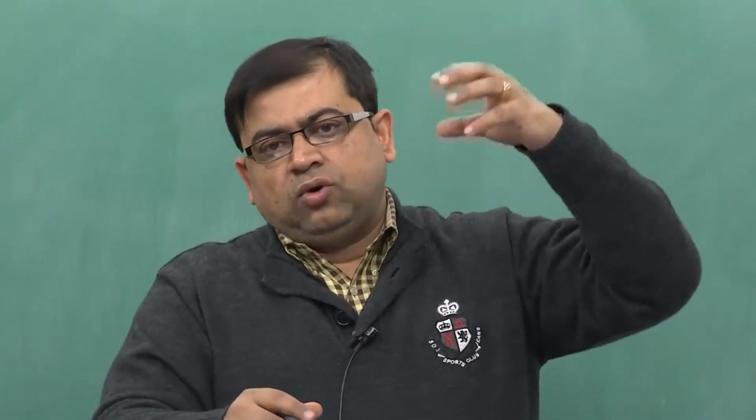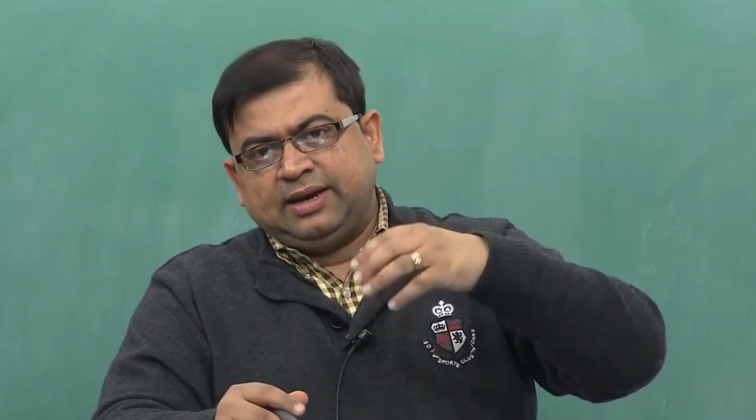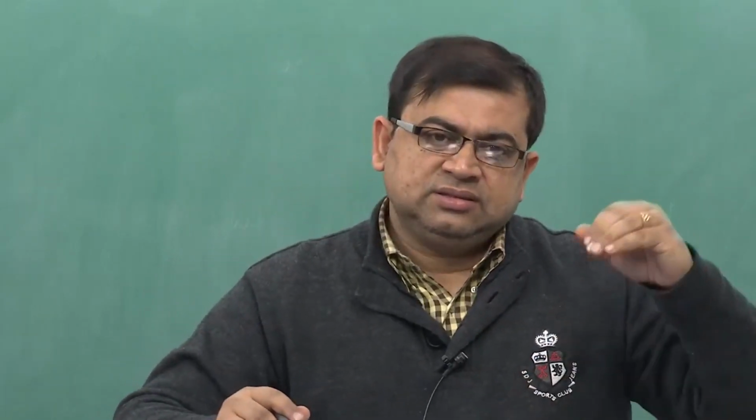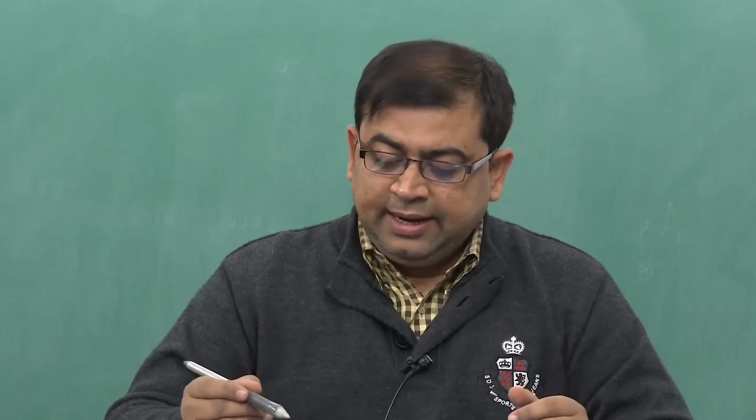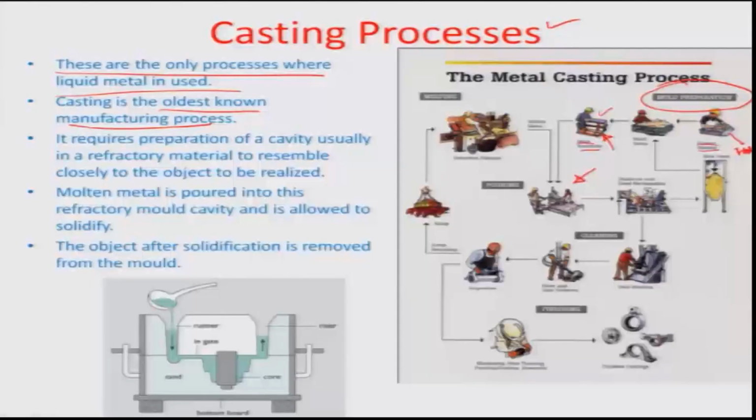So therefore this is a process really where you are trying to guide the liquid metal within this system of the mold, so that the material goes and comes into a cavity which is of the negative shape of the part that is to be produced, or the size that is to be produced, and that would really create the mold.